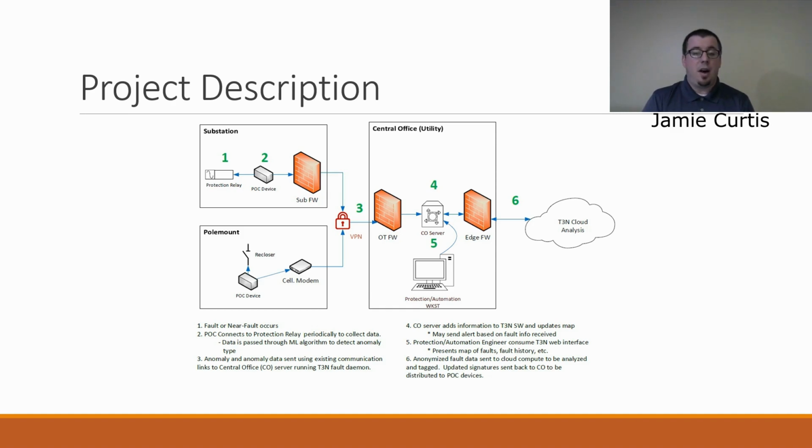The fault did not cause a breaker to operate, but was identified with high confidence as being a fault on phase A to ground, most likely due to intermittent tree interference. The utility schedules its vegetation management truck to include that site in its schedule the following day and cuts down the obstruction, preventing the possibility of a fire or an outage in that area. As you can tell, this is an ambitious project.